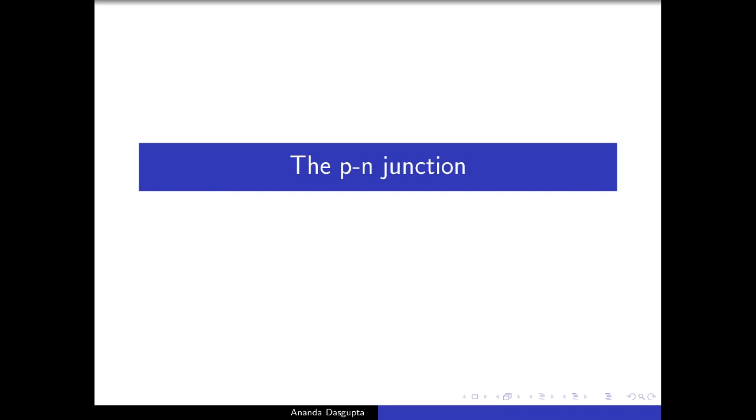If you made the anode positive with respect to the cathode, the electrons could flow because of the attraction of the positive anode, establishing a current in the circuit. If on the other hand you made the anode negative with respect to the cathode, the electrons were repelled and they could not make it onto the anode, hence no current.